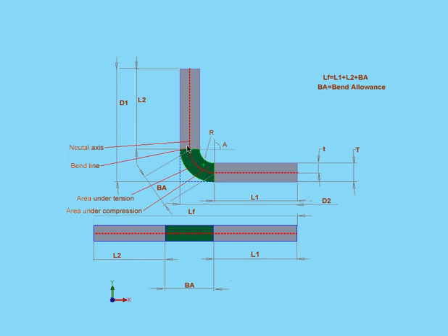The bend allowance region is shown in green in my diagram. This is a region where, in theory, all deformation occurs during the bending process. Generally, the bend allowance is going to be different for each combination of material type, material thickness, bend radius, bend angle, and different machining processes, types, speeds, and so on. Truly, the list of potential variables is very extensive.